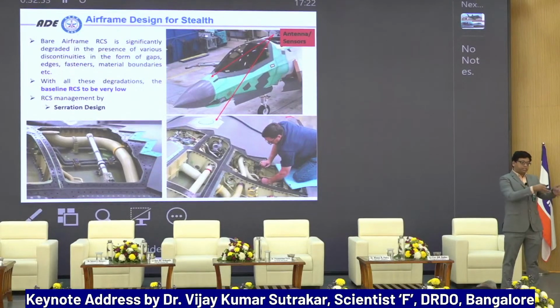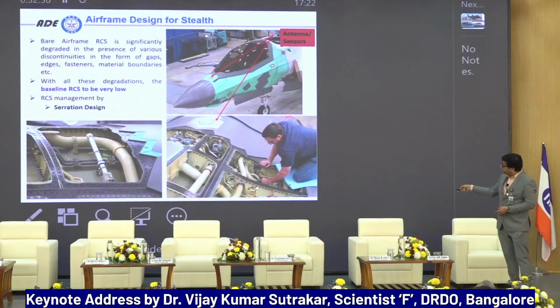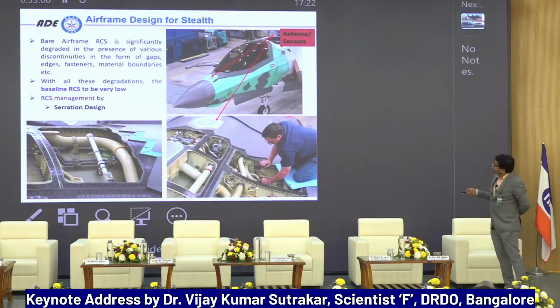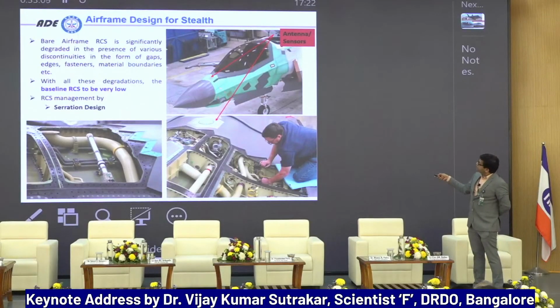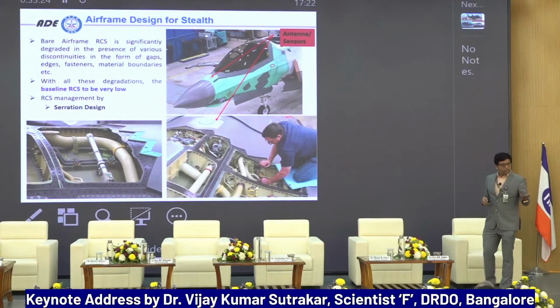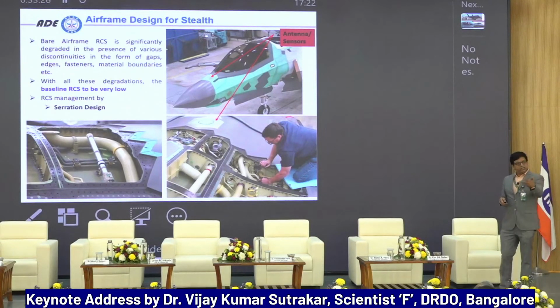So now my tool design, the tool is becoming longer, the part is becoming longer. So where you are mounting this skin, your frame size is becoming longer, so it may have a weight penalty issue. Also, if you notice here, I highlighted some places, those are all some of the antennas. Those are all conformal antennas. It's conformal, but now if you see the shape of that, it is some kind of diamond or hexagon shape. So how to make a cutout of the antenna is also important. It is not only the antenna design. Now the antenna has to mount onto the aircraft, which also has to be looked at critically.